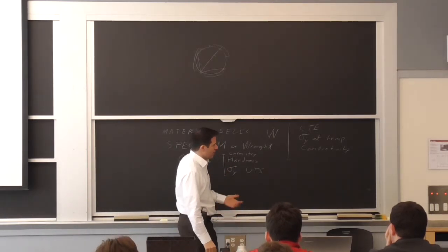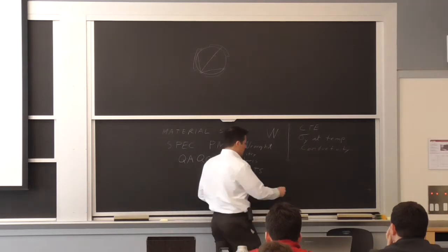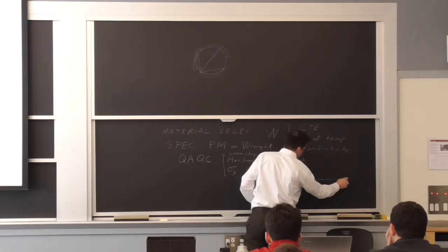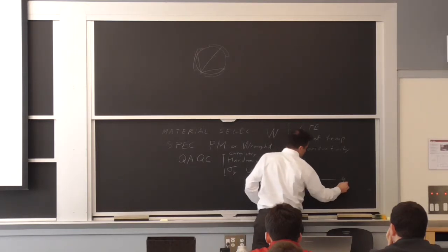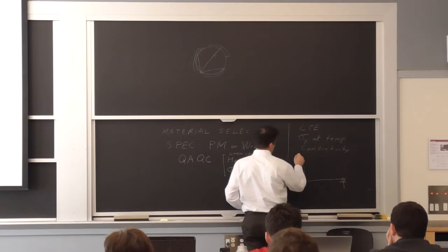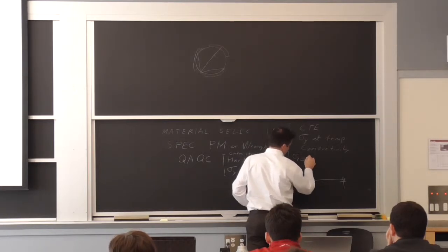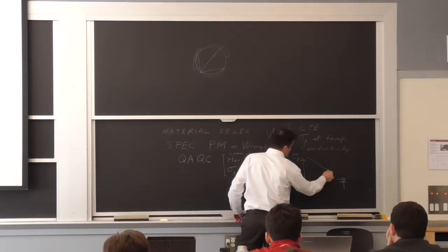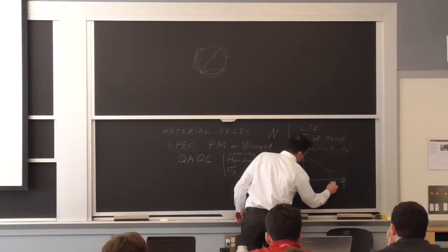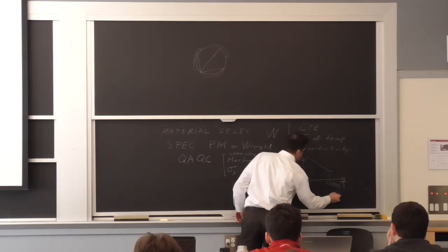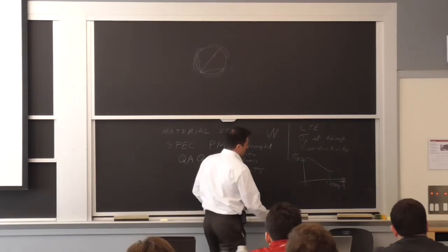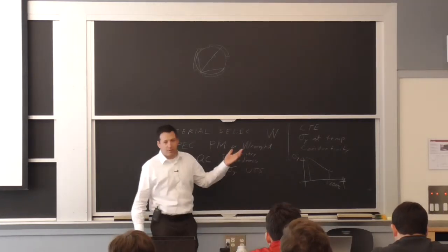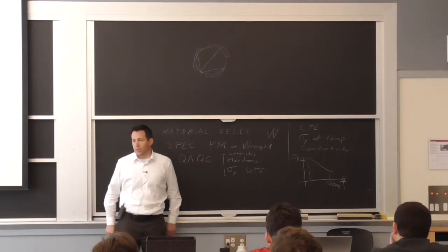the majority of the alloys, especially if you're using powder metallurgy or deformation processing, behave. If you look at what happens when you increase the temperature, your yield strength is going down. And there's only so much. If this is our temperature of 1200 degrees C, say we're designing for that here, there's only so much you can use your data at ambient temperature to say anything about what will happen when you heat it up.